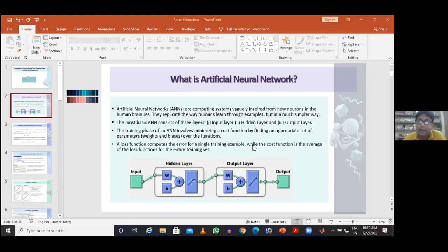If to achieve that speed there is an undershoot and overshoot, and it is not synchronized with the torque requirement, what will happen? Naturally, you understand that it will try to follow, but there will be some transient behavior. If the transient is more, your dynamic response is poor.